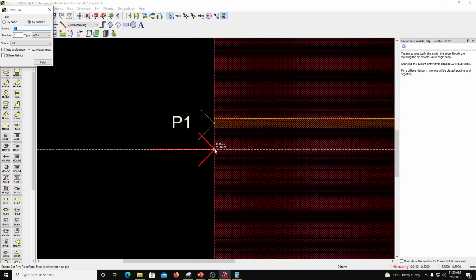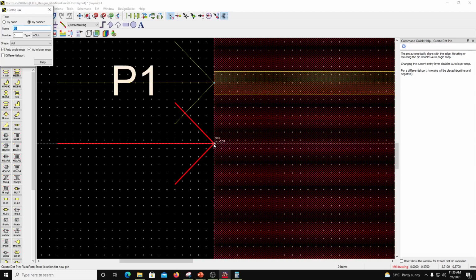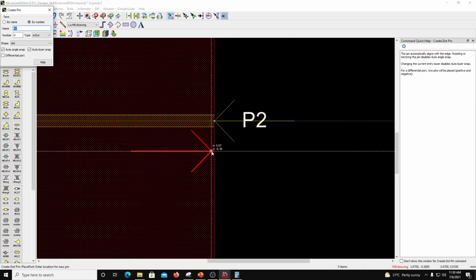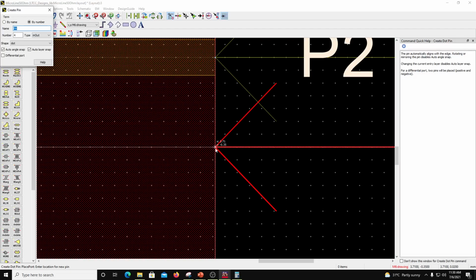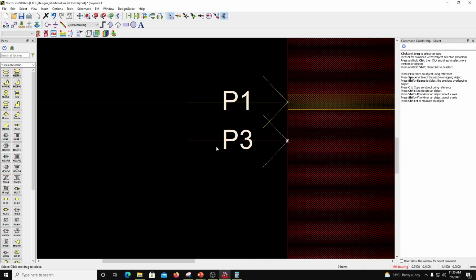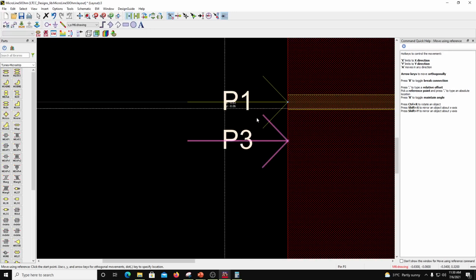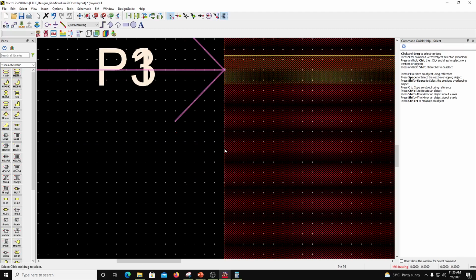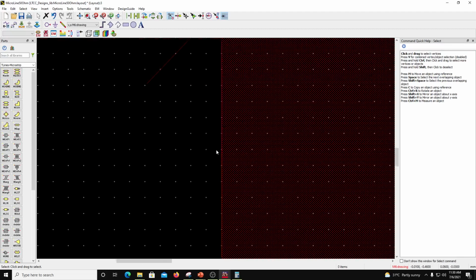Then I will need a ground reference. So I am going to do a snap to edge. So 3 is a ground reference for 1, and similarly I'll snap to there. This is a ground reference for 2. Now I can move this underneath the first one. So this is move. I can hold from here and move it under here, and you might have a line.